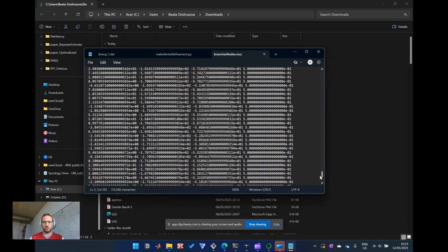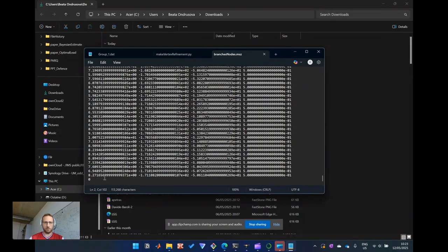And at the very end of this file, we're going to see a 0. So this kind of file dictates that for these points we would like to have a mesh size of 0.5, and that we chose to only refine for points and not for edges. That's why we have 0 edges that we decided to refine.